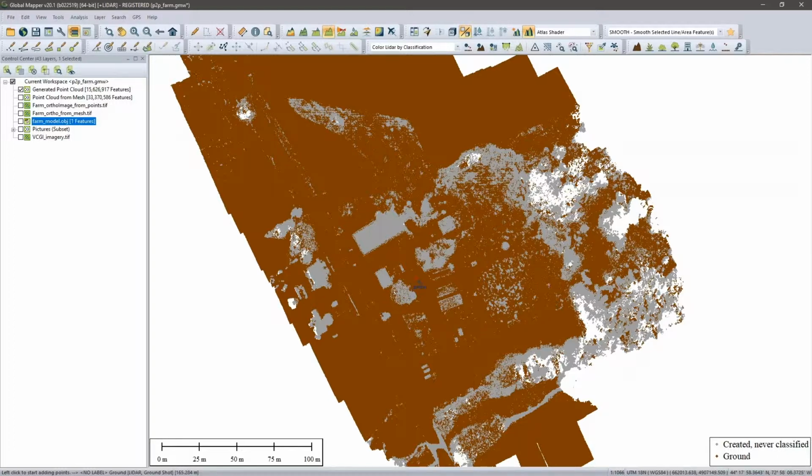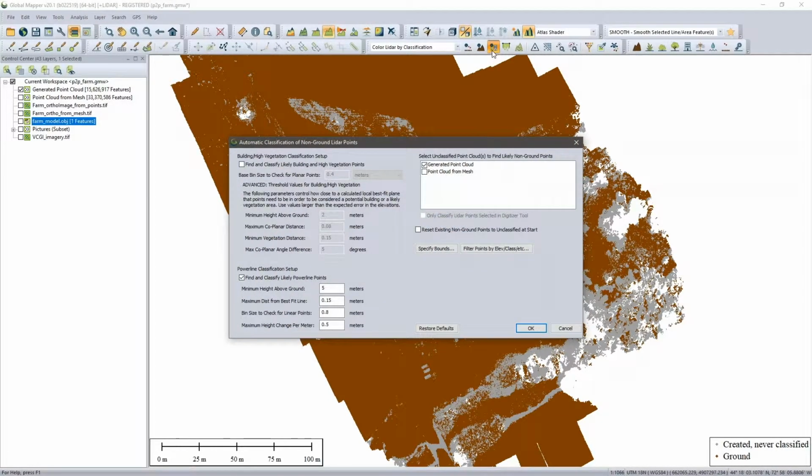Sure. So if I was going to create a bare earth model, a digital terrain model, I could just use the ground points here. So maybe that's what you're hinting at. In terms of actually classifying the buildings and trees, I won't go through this full algorithm, but we do have an algorithm that can identify trees as well as buildings, based on the point relationship. So I could do that. It can also do power lines with really high density data. So that would be another option. But we could actually classify buildings and trees.